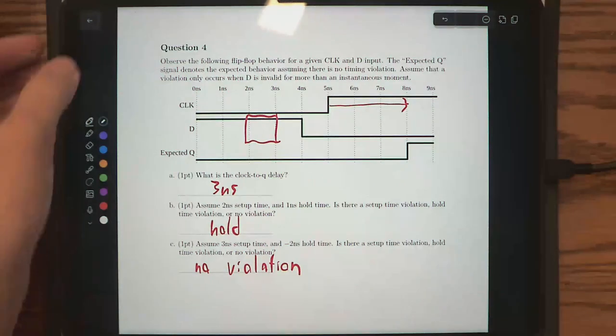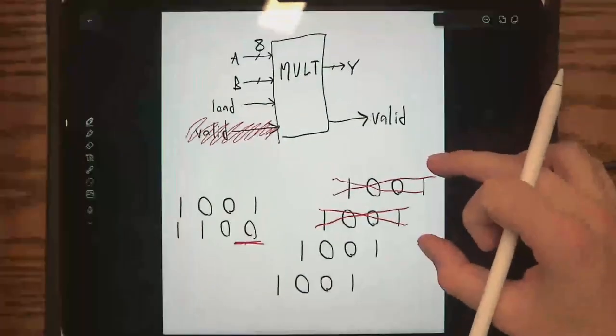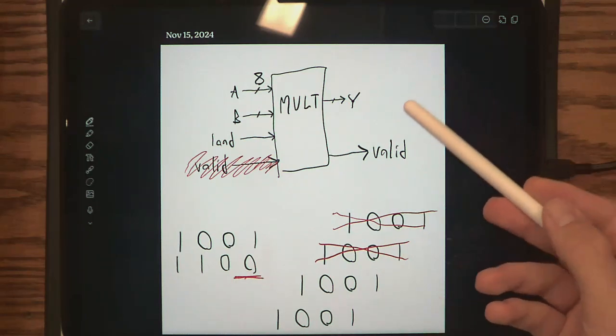Okay, cool. So I want to go back to an example that we did on Monday. On Monday, we were tasked with this problem where we wanted to make a more space-efficient multiplier. Because remember, the multiplier that we had made before used a ton of flip-flops, used a ton of adders. It was very fast, right? It passed the data through basically a hierarchy, like a tree of adders, and produced the multiplication output very quickly.